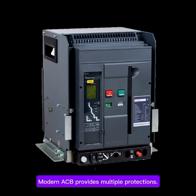Protection functions of ACB. Modern ACB provides multiple protections. 1. Overload protection, long time delay. L trips against overload current. Example, motor drawing 150% current continuously. 2. Short circuit protection, short time delay. S trips during heavy short circuit faults. 3. Instantaneous protection. Trips instantly during very high fault current.